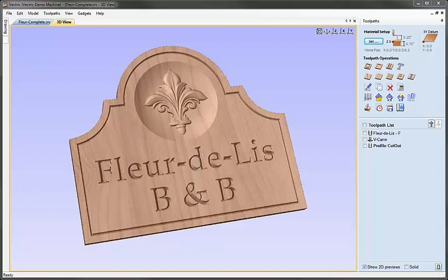We created a toolpath, in this case just a finishing toolpath to machine our dished area, and then showed you how to save that in a way where we're able to import it into Cut2D or VCarve Pro. We came back then into the software, showed you how to import that 3D toolpath file, and then we went ahead and changed its position, aligning it with the circle that we generated, and then calculated the toolpaths for our V-carving and our cutout toolpath around the outside of our job in order to finish all the toolpaths we needed to create the sign.